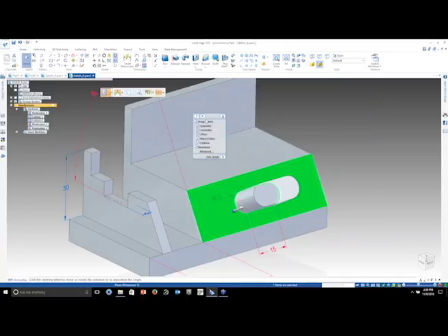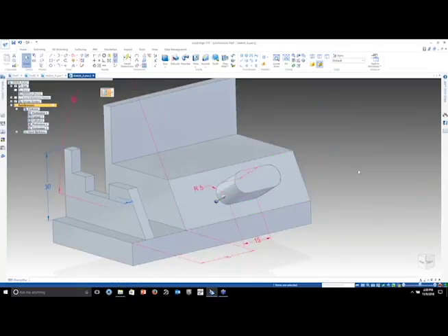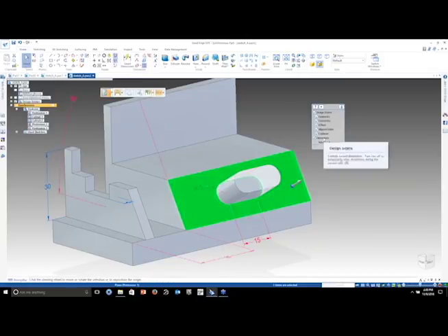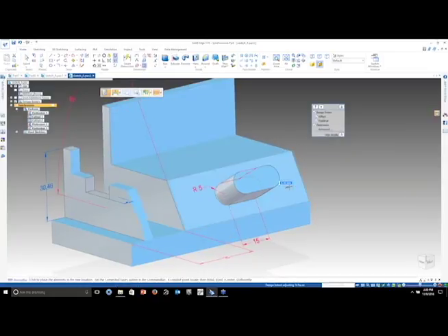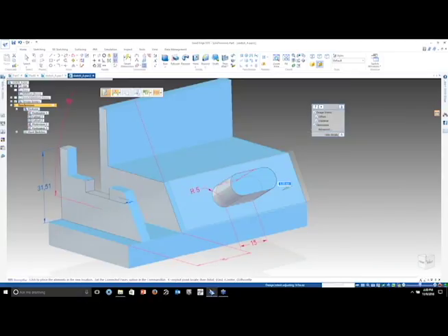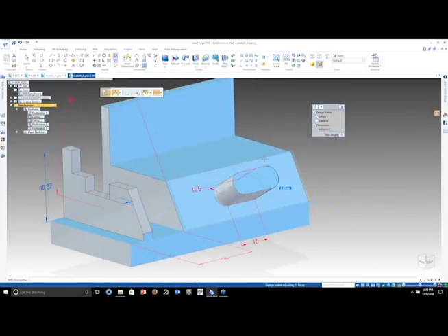So there's my geometry. Again, if you wanted to put dimensions on it at any given time, you can start adding dimensions to define your final product. And again, what's nice about this is it's synchronous. So we get this nice design intent that pops up anytime you pick a face. Let me just give you a quick rundown of how this works. All right, so when I grab a face, you get an arrow on it. You notice that we have some rules here that it's looking for. So it's looking for concentric faces, collinear faces, coplanar faces.